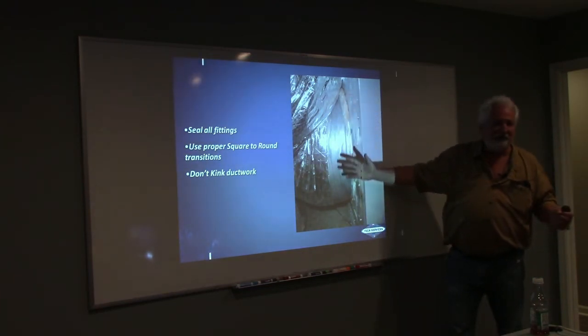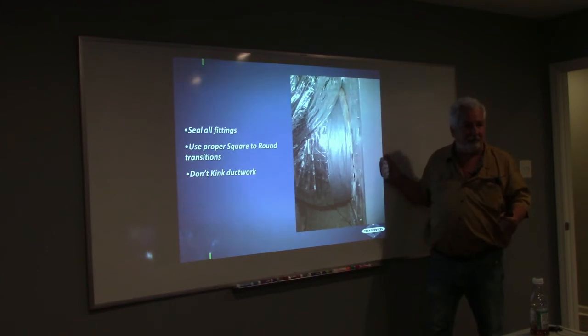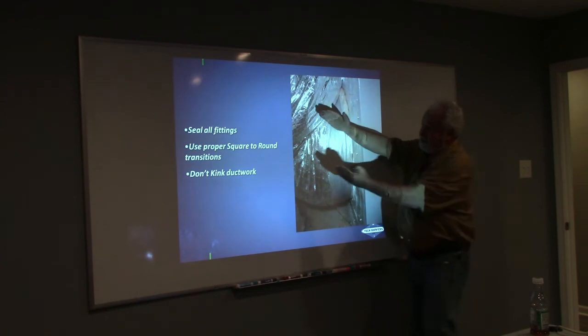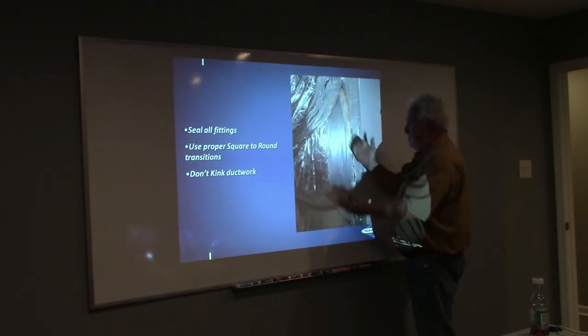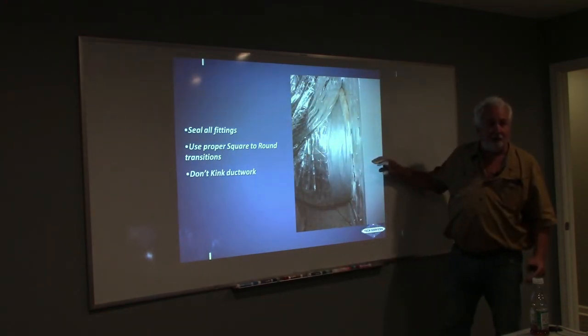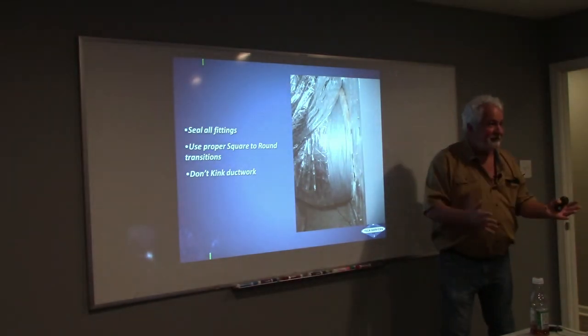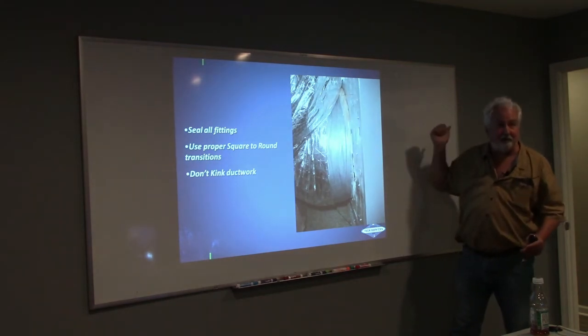The yolk's on you. So guys, look, here's those returns that they tie right onto the back. What's going to be the speed of that going to that evaporator coil? Well, I've got this much space. Great. He kinked it off. He did a 90. He came right into the back. I've got this much space. What's going to be the speed of that air? Fast. Good. What's going to be the quantity of air? Lower. Yeah, you seeing the difference. The speed is going to come in there. It's going to just knock that water right off of that coil. And blow into your cabin.